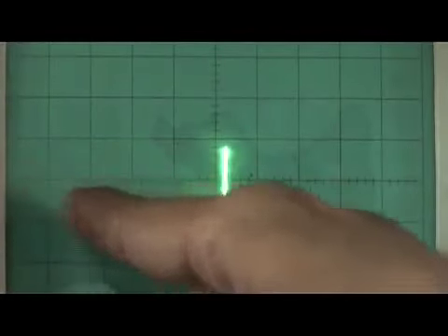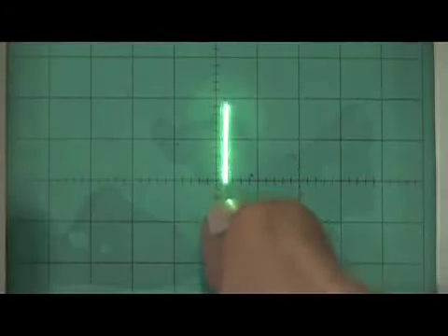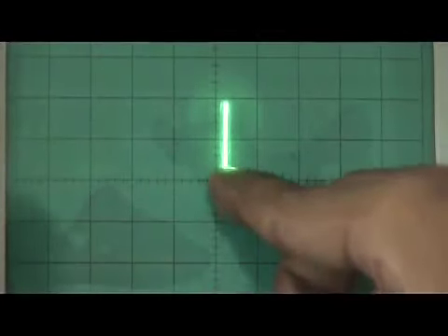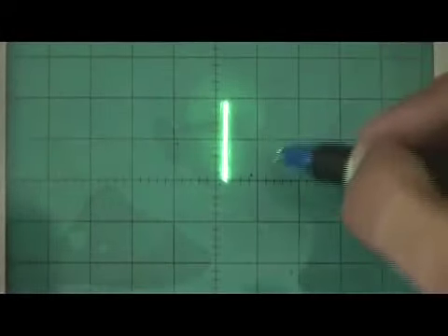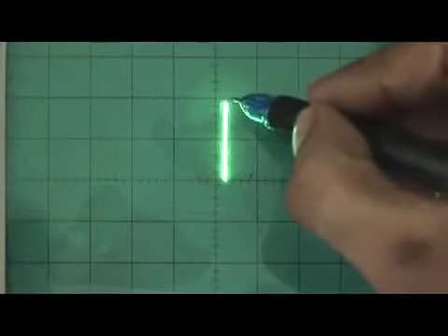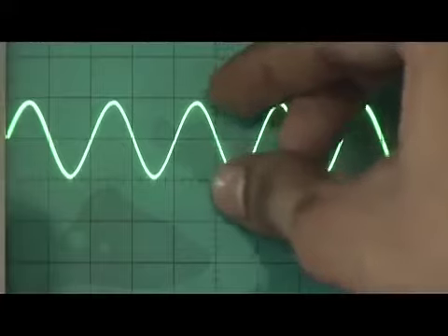Now, this dark black line, which has the subdivisions, is your reference line. Using this Y position knob you can move this line and bring it over here so that you can properly count the number of divisions. Now it is here. From here, if I count, it is complete till here, 1. From here it is 1.2, 1.4, 1.6, 1.8. It's almost touching 2 but not 2, so let us take it as 1.9. I release the XY. So it is 1.9 blocks that this amplitude is taking.